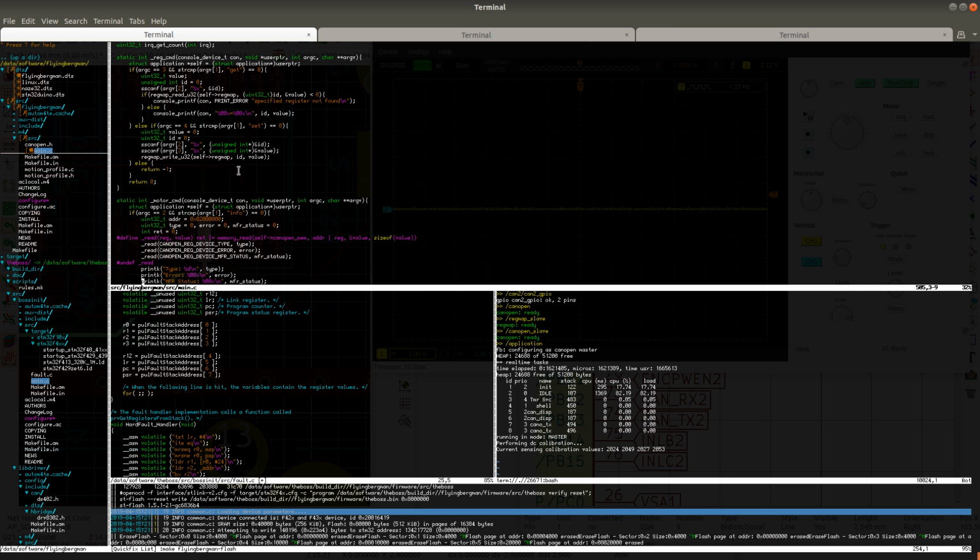Okay, so what I'll do is actually I'll read the inputs during the initialization, and then print out an error if running in master mode and some of the LEDs are not connected. But when it comes to actually debugging this, I think I'm gonna have to look at the datasheet and make sure that the SPI signal and the I2C signal are not somehow dependent, like maybe the peripheral flags, maybe something else is dependent somehow.